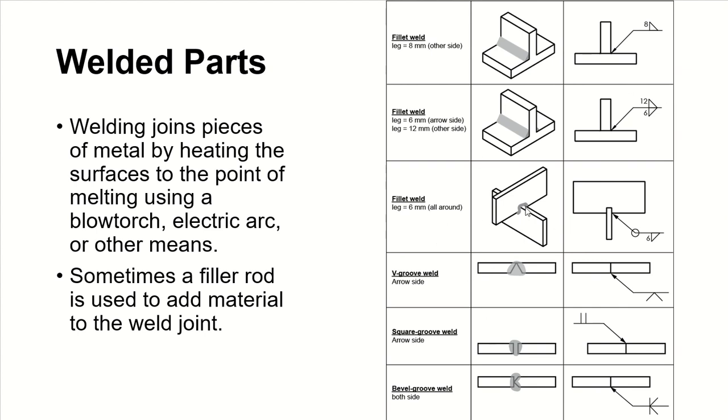Okay, so fillet weld, another one, because it's joining the two parts right here, and it says leg is 6 millimeter all around, from here all the way to the back. So just put an arrow right in here. We're going to use a different little symbol because it's just down. Here is up. Now we're showing the down. Weld is from the bottom, and you're going to put it down, and the leg is going to be 6 millimeter.